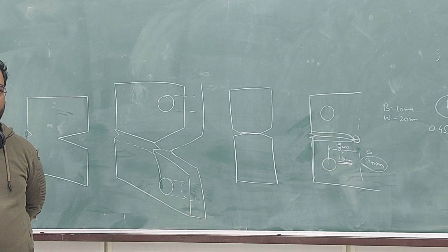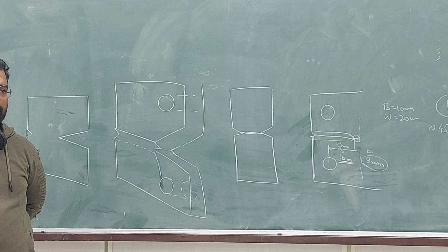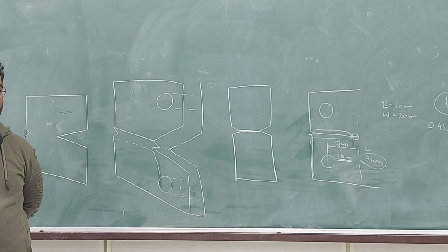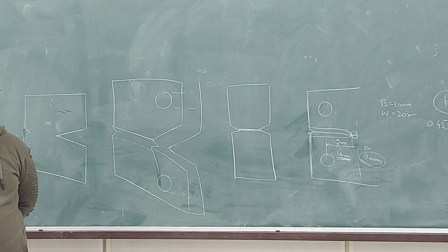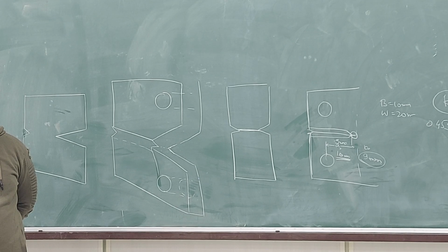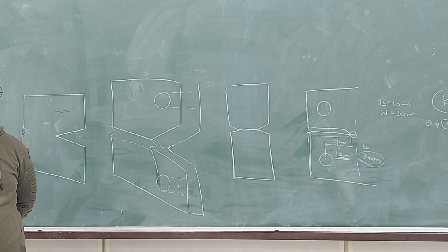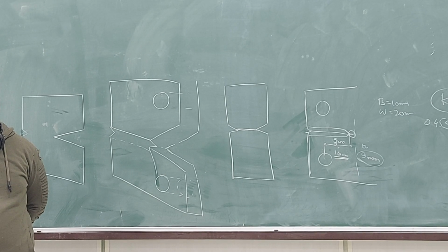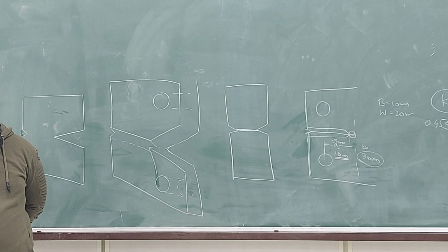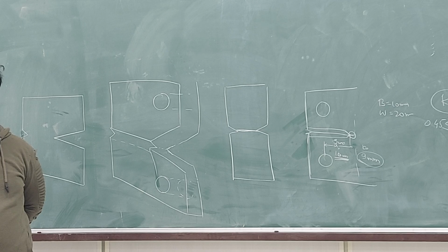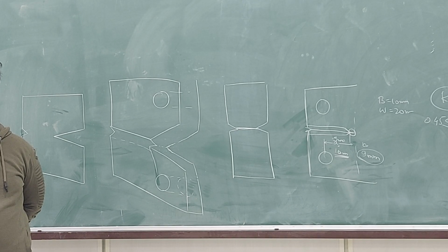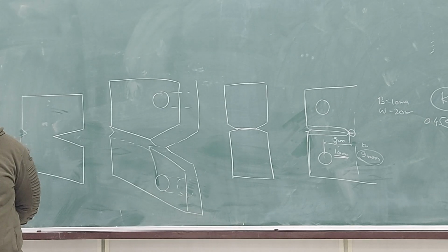Sir, I think in that case fatigue loading will not be possible. Why not? Sir, because the notch is very small, and sir, the compressive load might not be possible, sir. Why not? I can compress in a tensile sample, so why can't I in a notch? Sir, fatigue cracks can come on the surface. The crack will come on the surface from fatigue, and the notch front is the surface. So that is exactly where we want to bring the crack. And this argument would exist later also for the 1 millimeter.